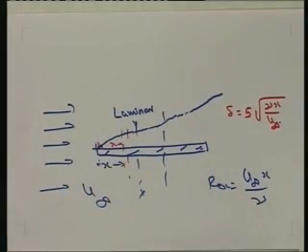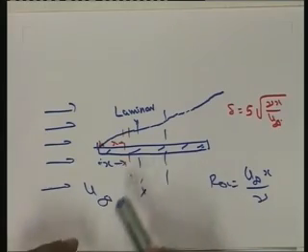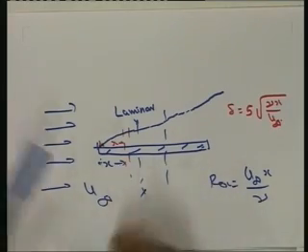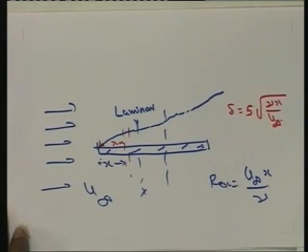So, this relationship derived by Blasius through various experiments we can utilize, and then if you define a critical Reynolds number from which onwards the flow is transition or turbulent, then we can put that condition. So, the boundary layer thickness delta. With respect to the figure here, as we have already shown, with respect to the boundary layer we can get various characteristics for this laminar boundary layer. So, the various characteristics are defined here.